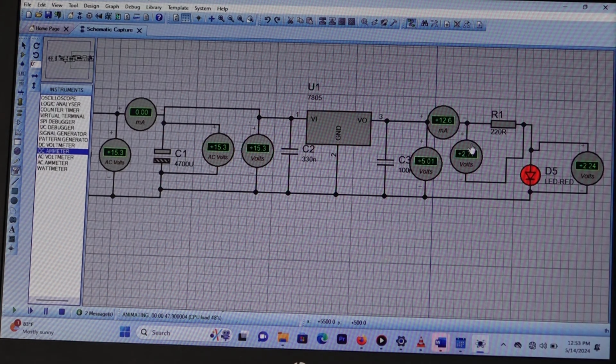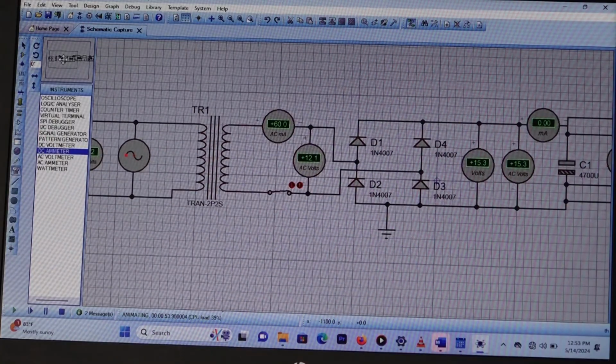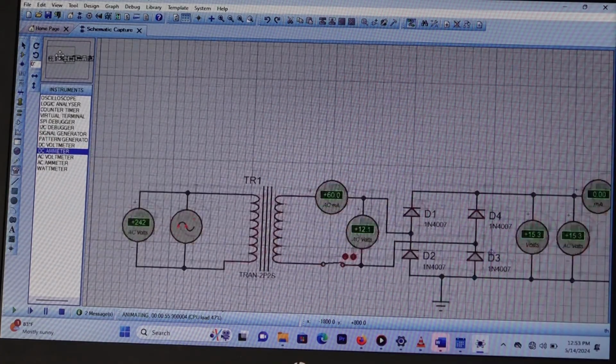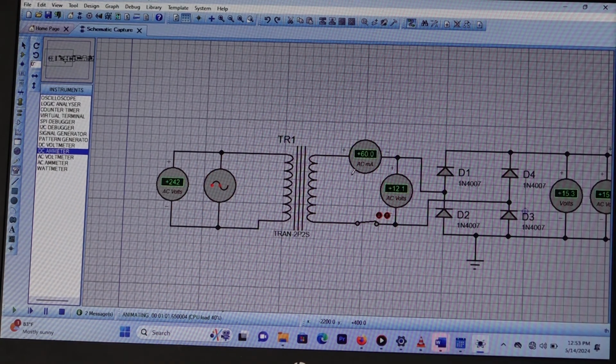Are we together? Yes. Okay. So let us track our circuit from the beginning, before we connected the power bank or the connectors. The supply voltage is 242, the output voltage is 12.1. Then you see that the output current of the step-down transformer is 60 milliampere. Why? Because as long as you are adding loads, more loads draw more current from the source.